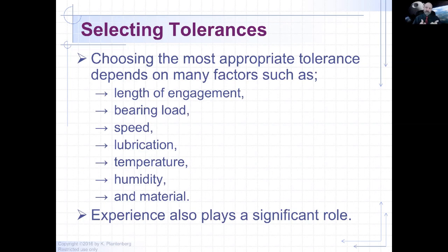And if the temperature goes up, the opposite happens. The shaft gets bigger, the hole gets smaller, I think. Let's think about that. Yeah, the hole gets smaller. Temperature goes down, the hole gets bigger, the shaft gets smaller. So you can see that it depends on what temperature you're going to run your part at. That'll be a determining factor on how you're going to tolerance something.